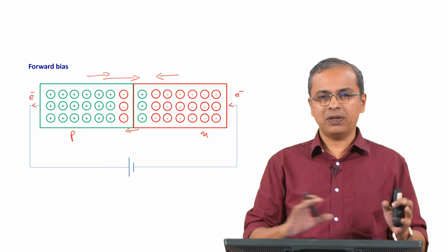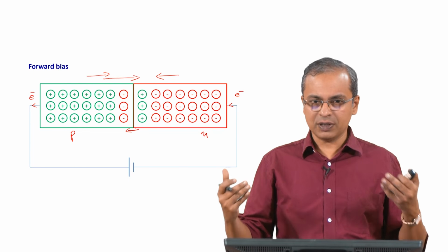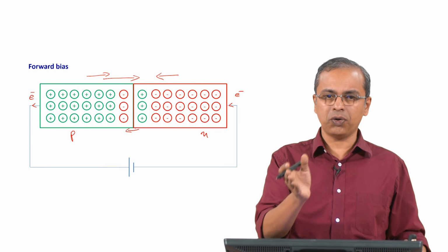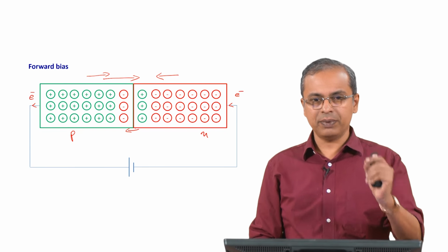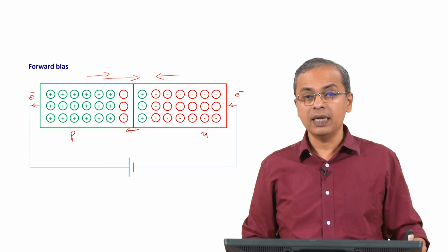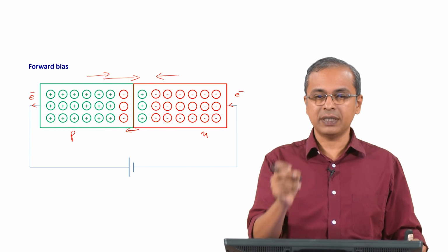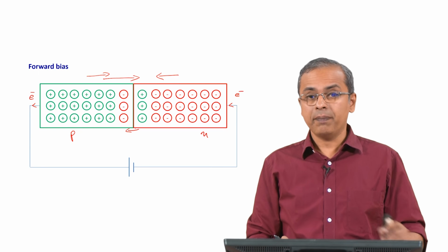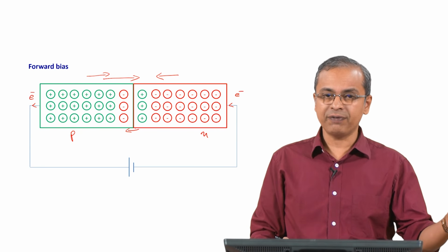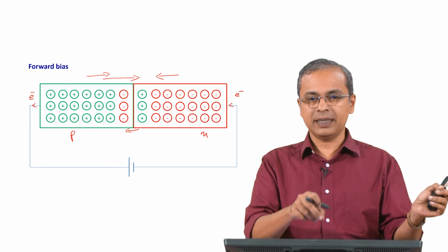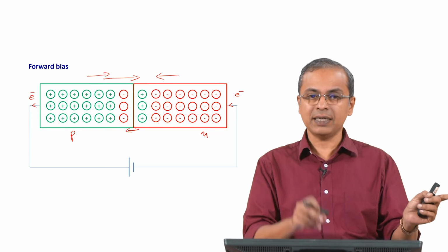But if you really want to not confuse yourself, you can think of it as an electron that is going through and through. As it crosses the junction, it occupies the location that was available where there was a hole, which means that hole has now disappeared. That hole is no longer there because an electron is now sitting there. But if you slowly draw that electron away to your left and remove it from that region, you have again brought back that hole. That missing bonding electron is still there. So, you have brought back a hole.